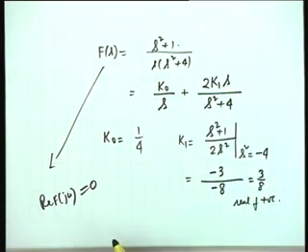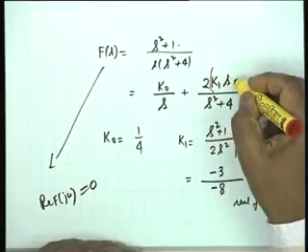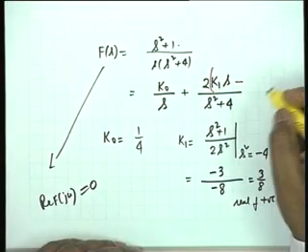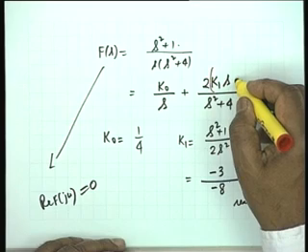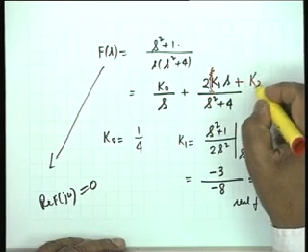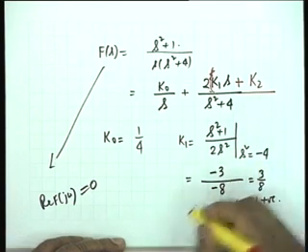So, while doing the partial fraction expansion, in the second term we should assume 2k1s plus k2, some constant. We cannot directly assume it to be positive real and assume k2 is equal to 0. Can I? That is a good question. Why do we write 2k1s? Because we take the two poles separately and add such terms. No, but there was a constant term. You recall that this was k1s minus k2 times omega 0, that is 2k2. So, in all fairness, you should have written this as 2k1s plus k2 and discovered that k2 equals 0.